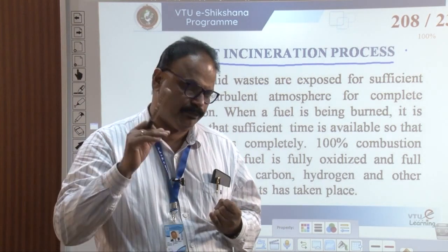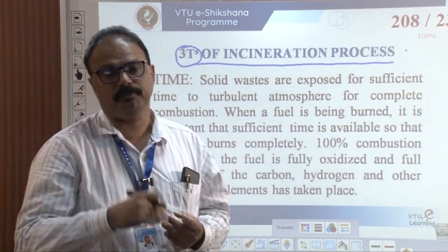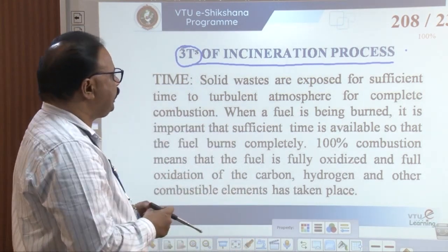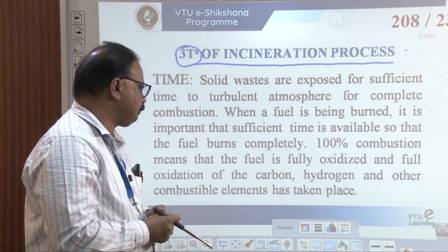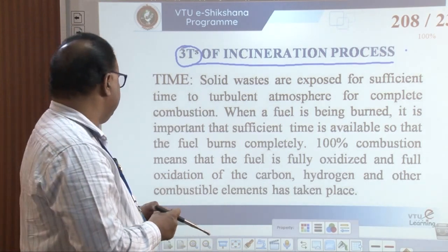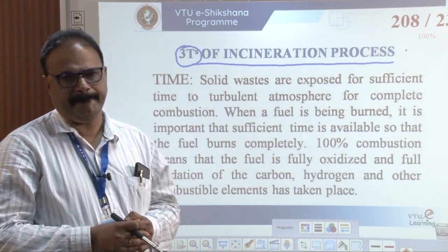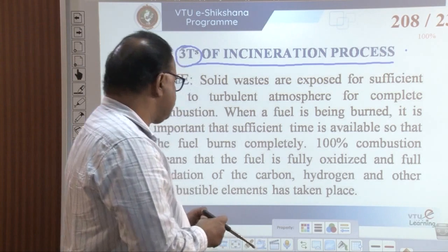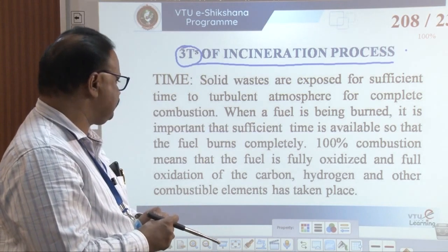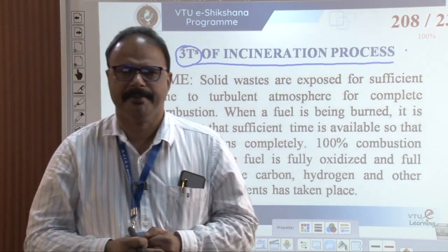What is the importance of time? What is the importance of temperature? What is the importance of turbulence? This is important: solids must be exposed for sufficient time to a turbulent atmosphere for complete combustion. When a fuel is being burned, it is important that sufficient time is available for the fuel to burn completely. 100% combustion means the fuel is fully oxidized.